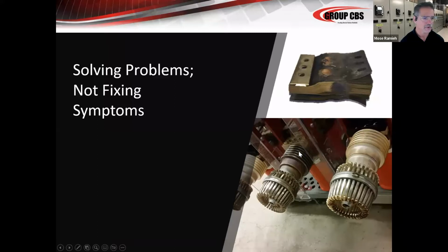And once again, everybody can see this is a medium voltage vacuum breaker, with a discolored pole here and a nice shiny pole there. A company had condemned this entire breaker, saying it needed to be replaced, and that's an expensive component, as you might imagine. We got asked to give them a second opinion. Our technicians did a little more diagnostic testing and found that it was not an entire bad vacuum bottle and pole assembly, but the flexible strap connected to the bottom of the vacuum bottle. So we were able to fix this for a few thousand dollars as opposed to tens of thousands of dollars.